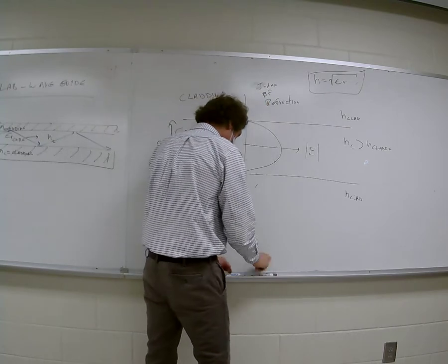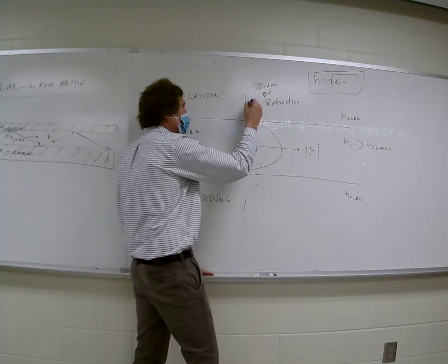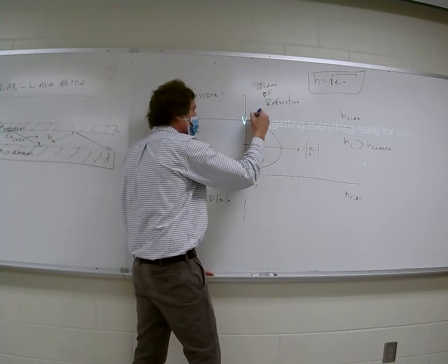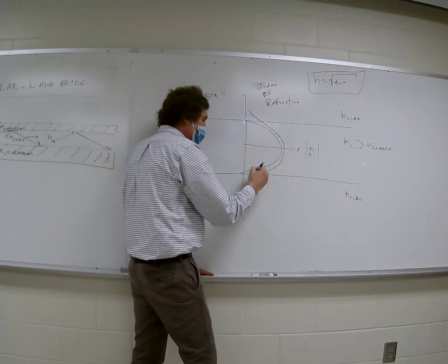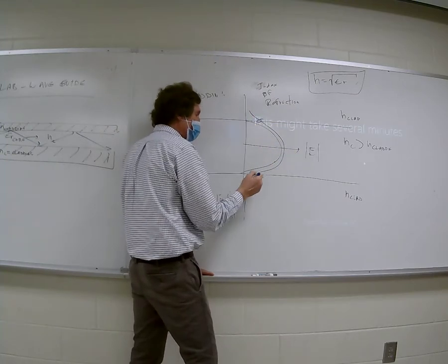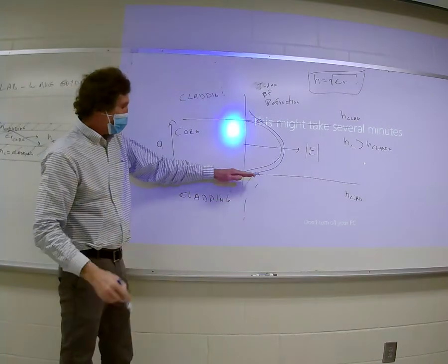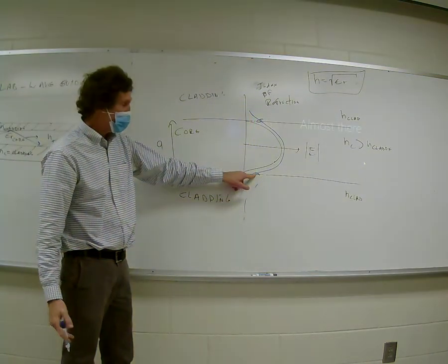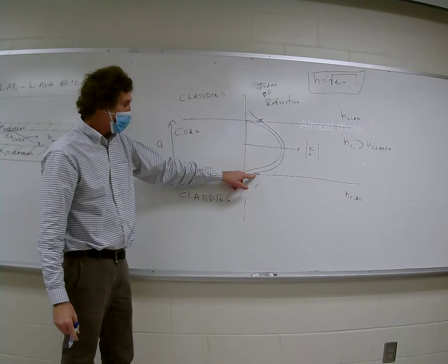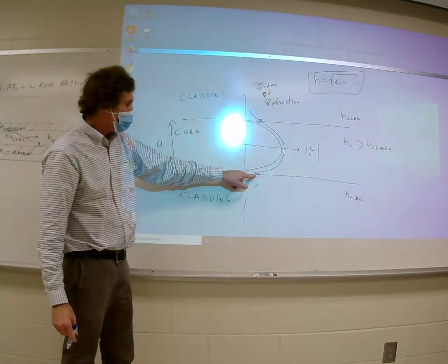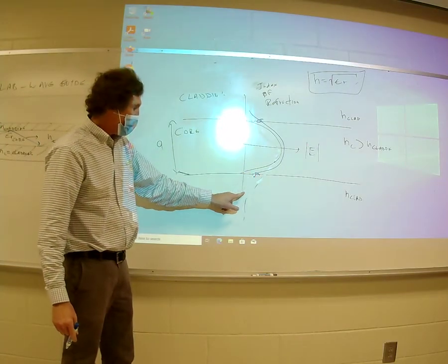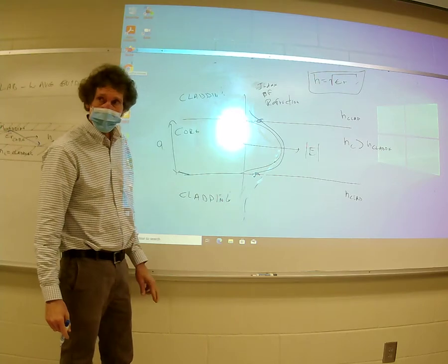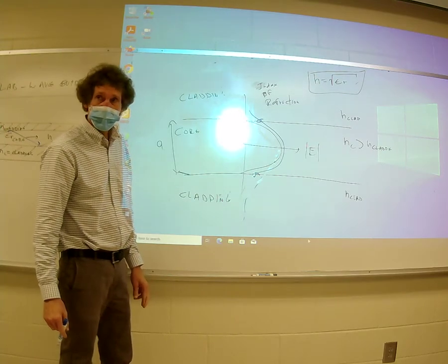You'll get bleed over. It'll look like a half wavelength, but it'll do this. And what you'll see is the fields here and here. For a rectangular waveguide, they go to 0. For a dielectric slab or a fiber optic pipe, they don't go to 0. What happens is they die out exponentially in this direction. It's called an evanescent mode. Do you all see that?